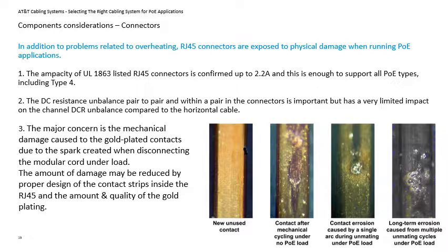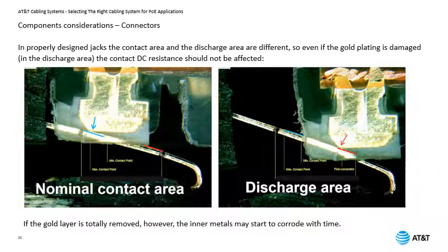As shown in the previous slide, the pictures clearly show the corrosion that happened due to unmating the RJ45 connector and plug while PoE is active.